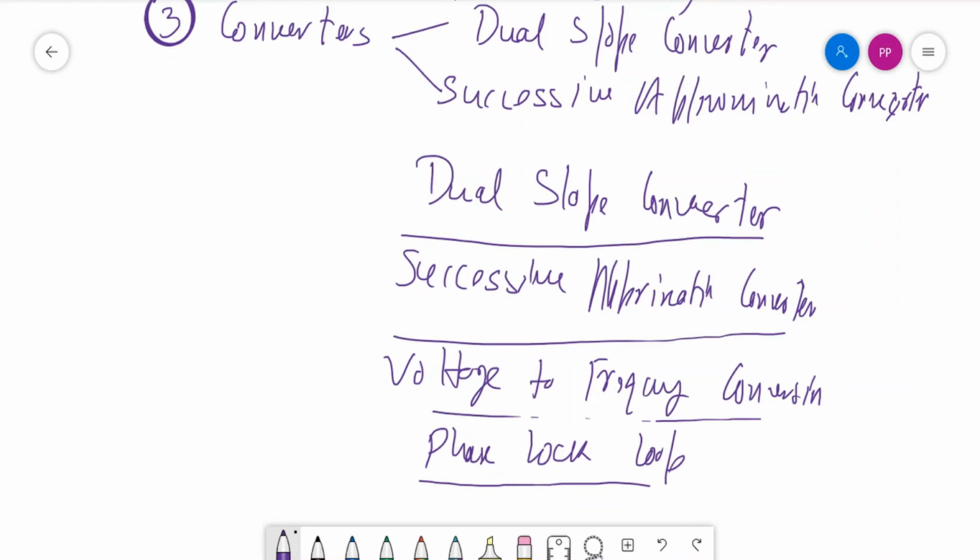So here the input voltage is of DC type, which has to be compared using a comparator, and the output of the comparator goes to the voltage controlled oscillator, and thus the phase or frequency of the oscillator is sensed by the phase detector circuit, and this circuit will generate an equivalent voltage which is compared with the DC input voltage. Thus the comparison of the phase detector output and the input DC voltage will generate an error signal that will gradually change the output phase of the voltage controlled oscillator.